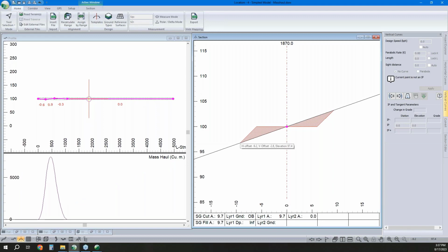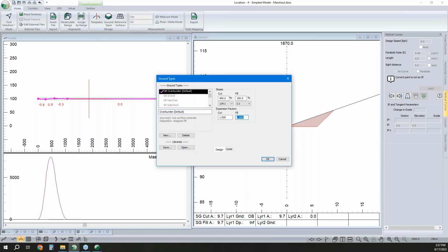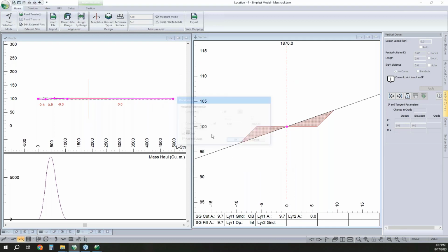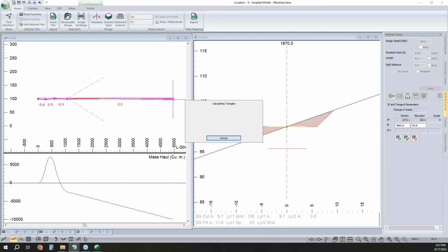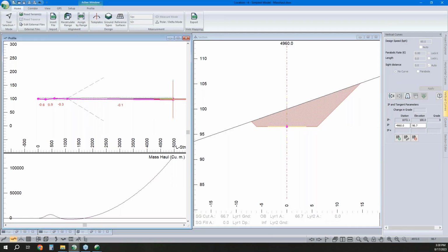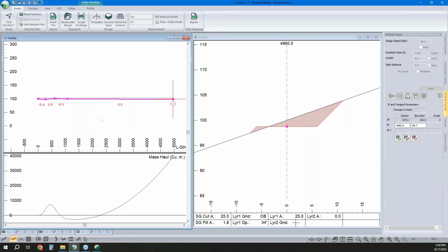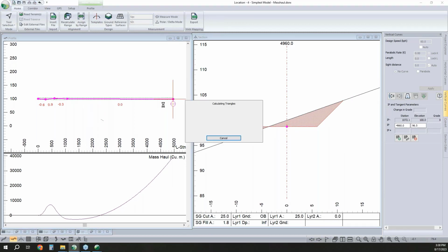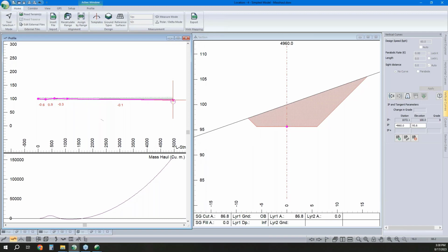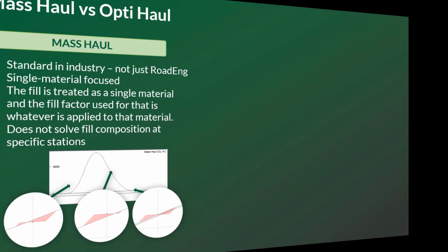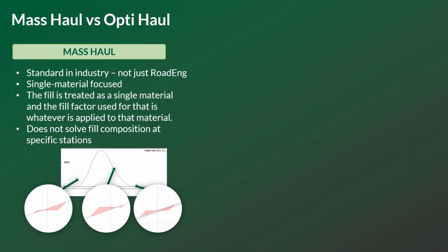The last thing to mention here is it does influence not just the volumes, but where you should put the road. So I jumped the gun. We'll put that back to 1.2. Ultimately, if we want to design and have our road balance, we're going to probably consider dropping the grade. And so we end up chasing that balance to get things to equate. I won't bore you with the details as I move that around, but with that, I'll send it back to Aaron and we'll get into the either more boring or more interesting stuff, depending on which group you fall in.